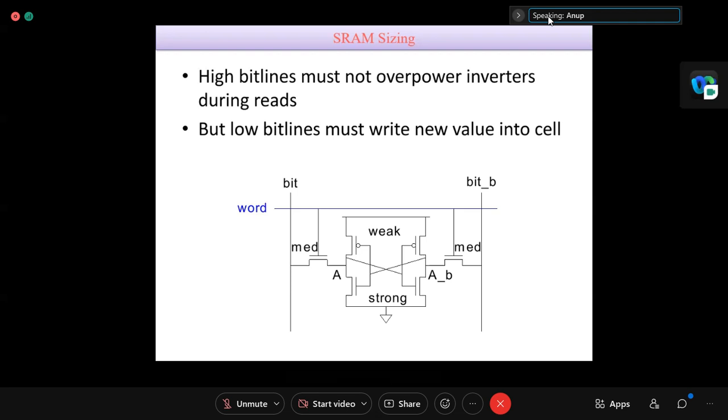And in case of PMOS, it is again another 2.5 times that of NMOS. Normally we take 2 to 3 times. So widths are more. So if you are changing, I mean weak or strong, it is in terms of sizes. Sizes means, to be very specific, in terms of more width.